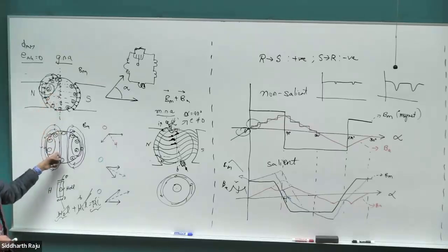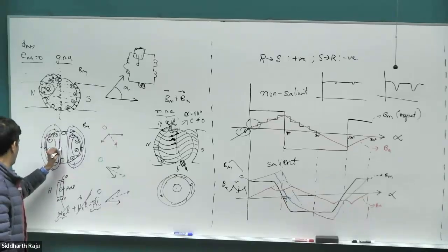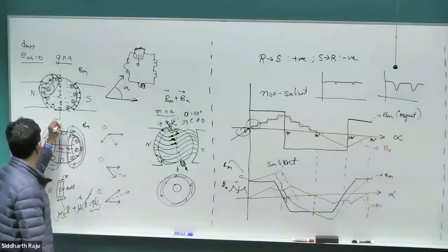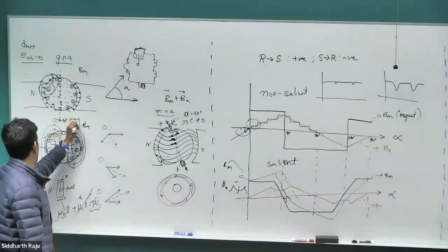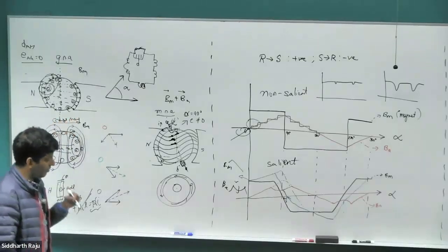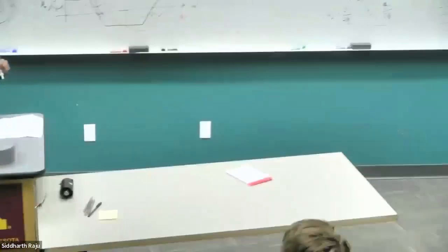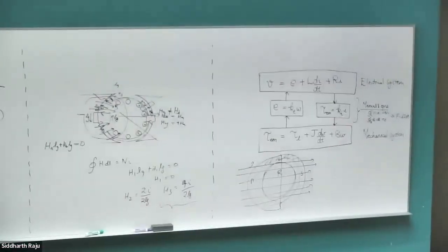Compared to the drawing on the top, what is the direction of the field lines inside the rotor core? Perpendicular. Right? Our external field is in this direction, our B field inside the rotor is in perpendicular direction. So this is called the cross magnetization field. And if we have components in the direct axis, then we'll call it direct magnetization field, which we'll look at in a minute.